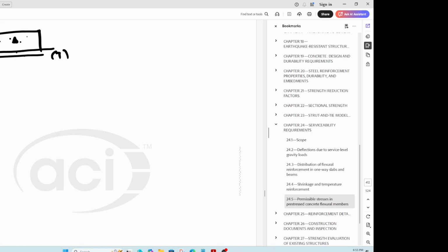So that's your concrete there, right? And it hardens and it becomes like that. This is aggregate, right? Now you come back and cut the reinforcement so that you can use the beam. Now that you cut the reinforcement, the tension will get translated. I mean, the reinforcement is wanting to retract, and it is applying a compressive force here.